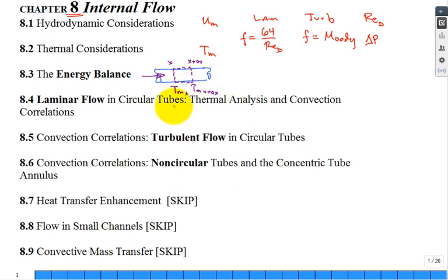is real important. So if I said, what is the rate at which it's flowing in on the left at location x, it would be the product of the mass flow rate, specific heat, and you have T minus a reference temperature, but often we even just drop off that reference temperature. It's going to cancel out of the equations, but it's just m dot C T. Hey, what is m dot? Mass flow rate. What's C? Specific heat. What's T? Temperature. It's like m dot times its enthalpy, if you're thinking Thermo 1.